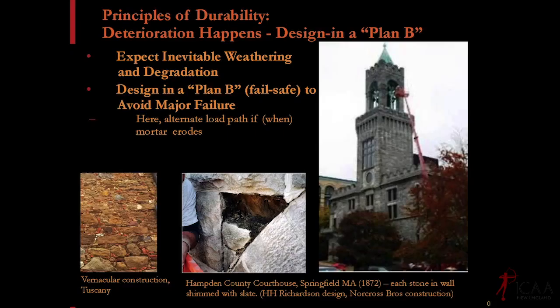One example on another Richardson building, this is the Hampden County Courthouse out in Springfield, Mass. Another Richardson building built, like almost all his buildings, by Norcross Brothers, who I think were just very, very good contractors, and they realized all this. So even though this was ashlar instead of stone masonry, there was basically nothing left of this mortar after 140 years.